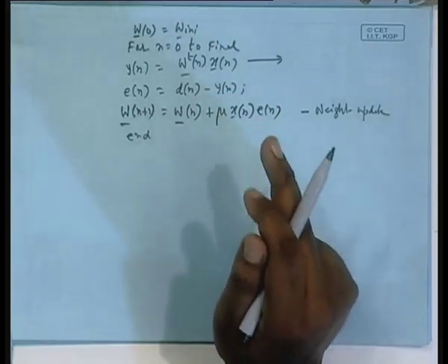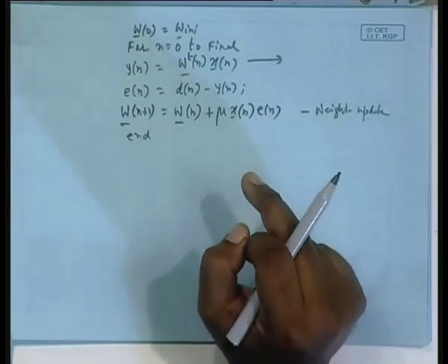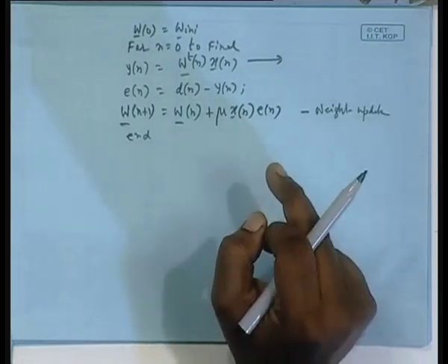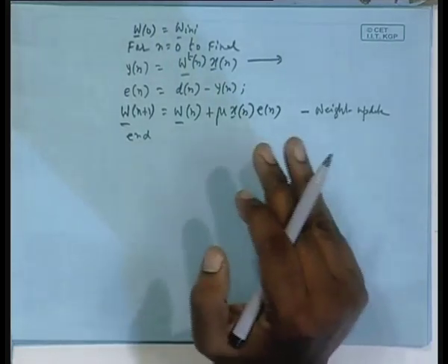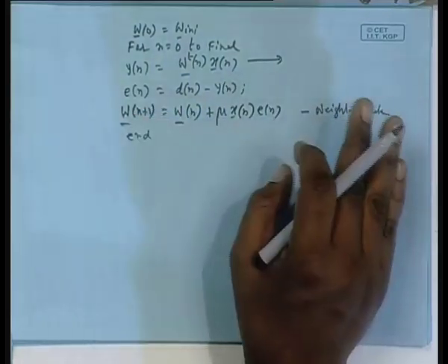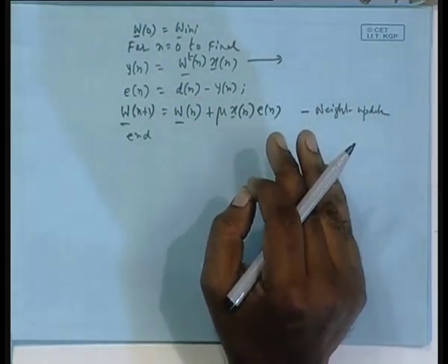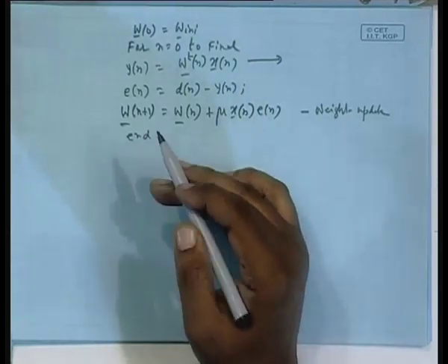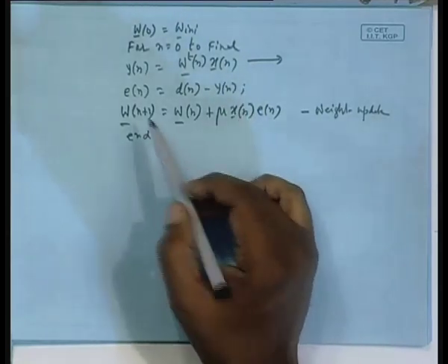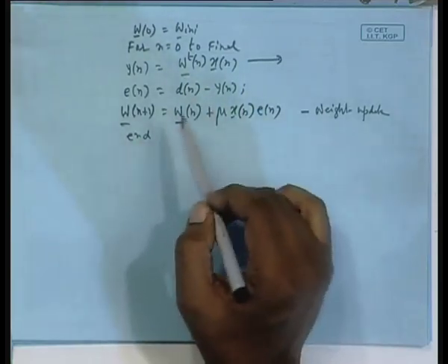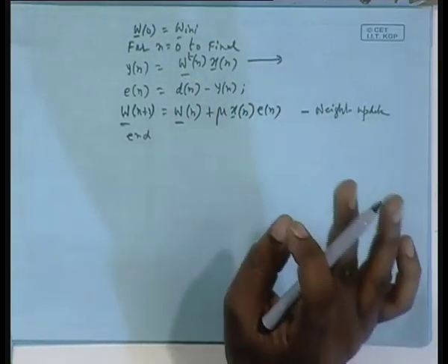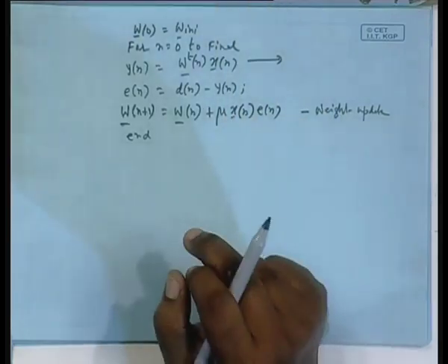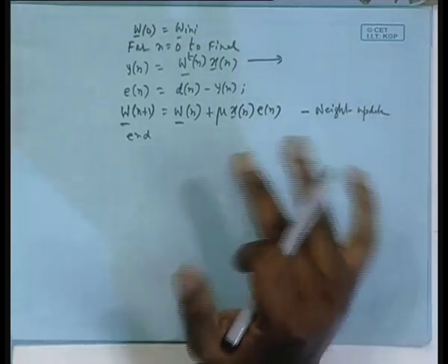This is the most celebrated algorithm, spend some time on it. This is called the LMS algorithm, the basic LMS algorithm. It is by far the most popular algorithm. In the 80s, another class came up, totally different in approach and derivation, called recursive least squares, which gives a more accurate estimate and faster convergence. Like here, w will go on iteratively, and we will show that it will converge, but that algorithm, RLS, recursive least squares, gives faster convergence, but it has some problems in structure and all that. It is not easy to implement.